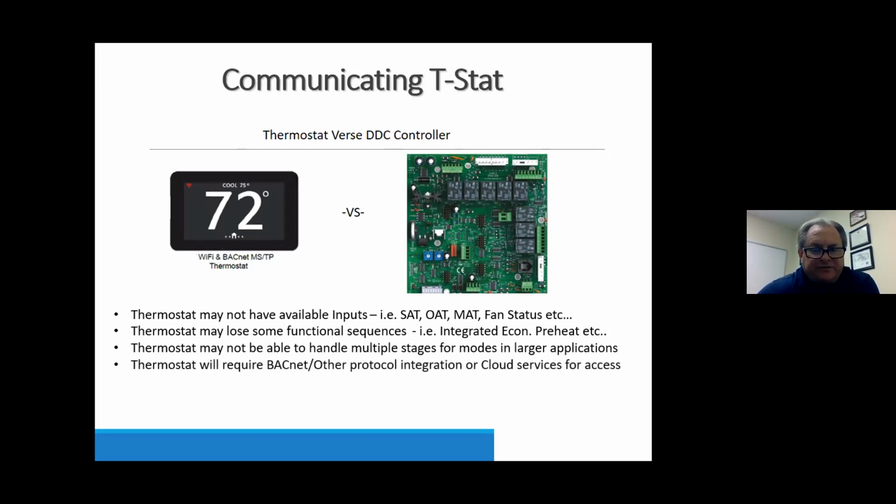Okay. And then keep this in mind. We talked about it. If you are using a lighter DDC application for a function, whether it be, let's say, bar units or through-the-wall equipment, things of that nature, every one of those thermostats needs to be brought into a front end. And in order for them to be brought in through a front end, it has to have some kind of a BACnet protocol conversion. So something has to sit on that front end that says, okay, I'm going to take the BACnet information out of this thermostat and bring it into a web server. So somebody has to do that. A company that's providing that has to have that knowledge and that technology to do that in all those applications. Or it can be done through a cloud, which is owned by a service provider, not necessarily the owner. So those are some things that the thermostat DDC world has in store for you.